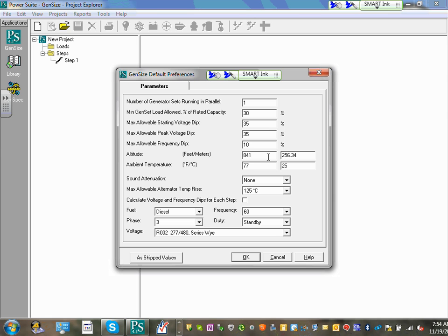Because if you put it in the Himalayas, the pressure is low on these generators, and they will be working harder. So you have to derate them. The higher the elevation of the generator is, the more the manufacturer has to take this into consideration, because the generator will be stressed. Did you guys hear me? The generator will be stressed.